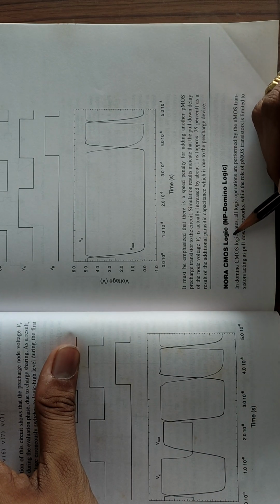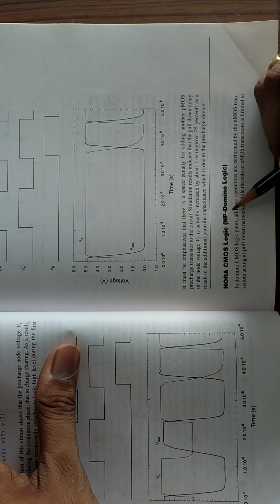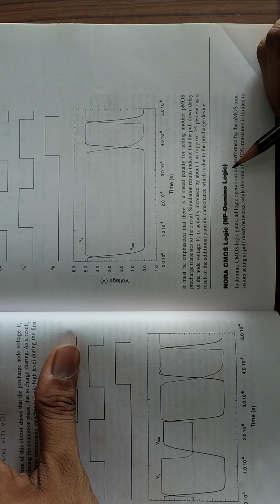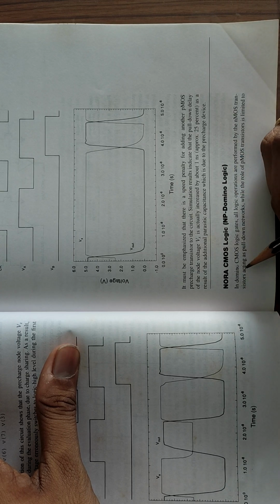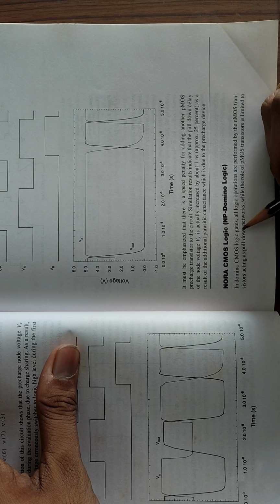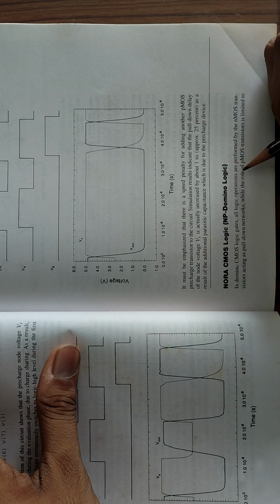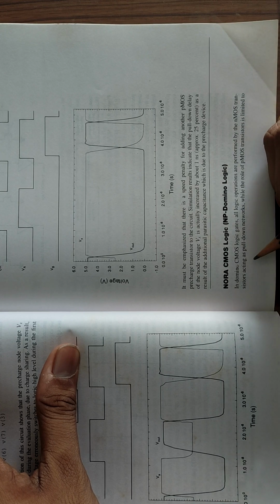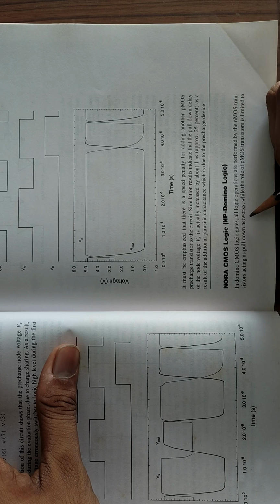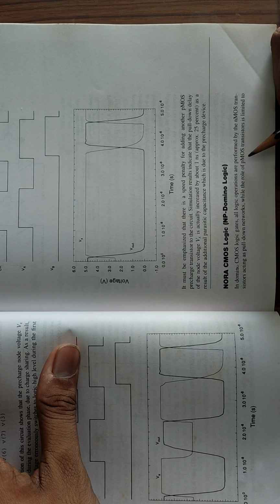NORA CMOS logic, NP-Domino logic. In domino CMOS logic gates, all logic operations are performed by the NMOS transistors acting as pull-down networks, while the role of PMOS transistors is limited to